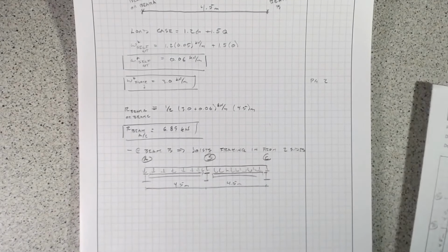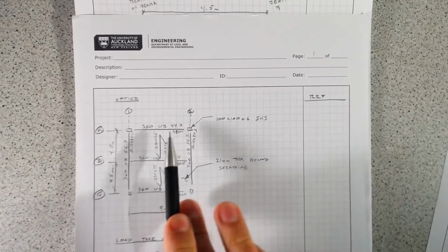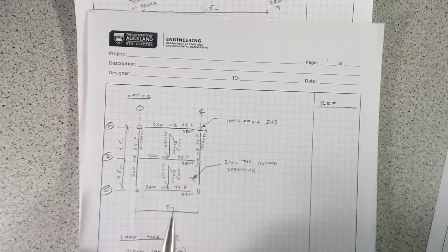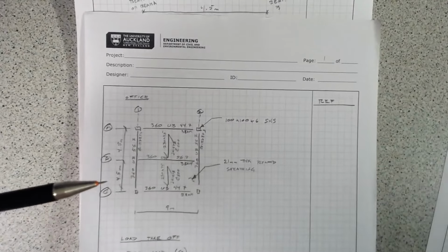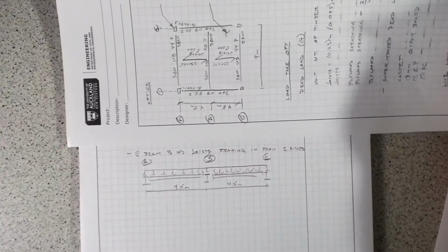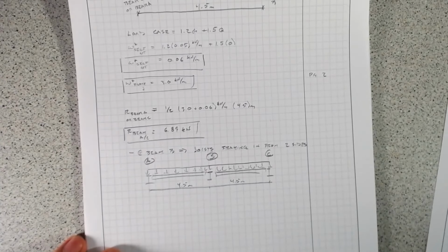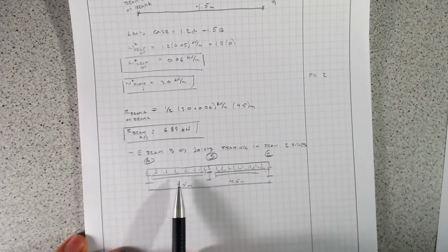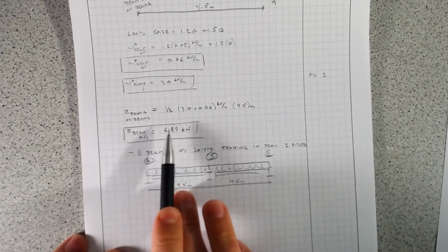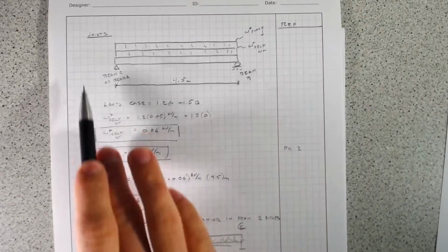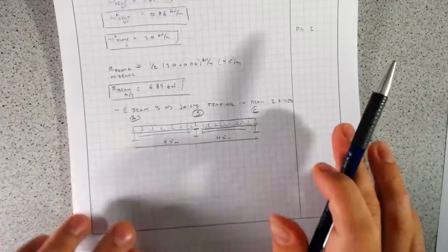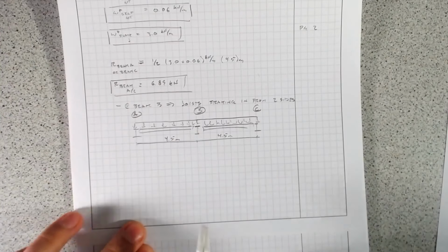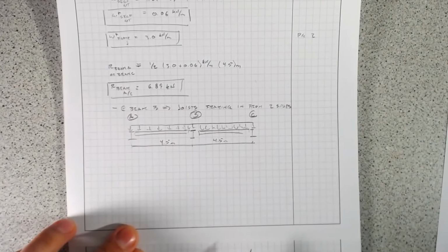And so that's just, again, showing a sort of a cross-section view. If I were to take a cut through this way and then look back that direction, you can see just like that. So, that's pretty straightforward. That means that we've got a symmetric beam here, so we know that both sides are going to have the same reaction. So on the beam at B, we just have to double this value here.